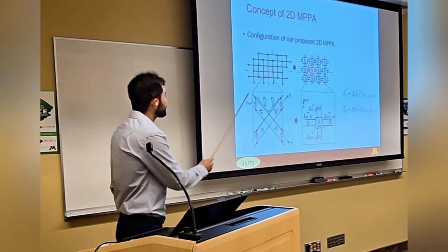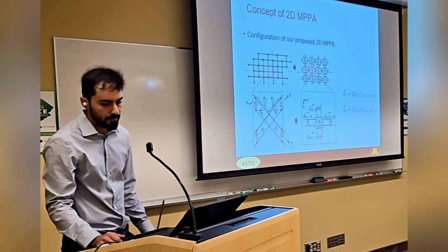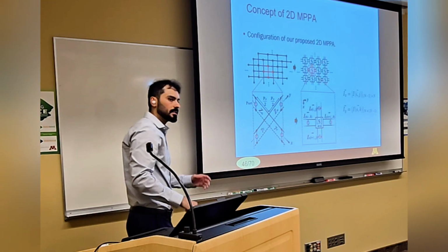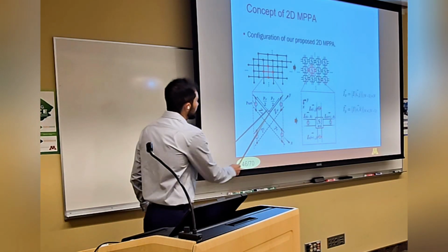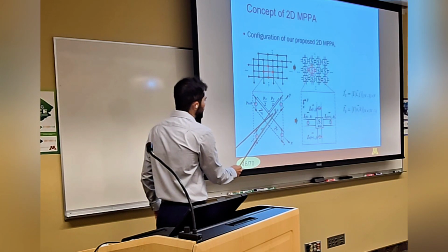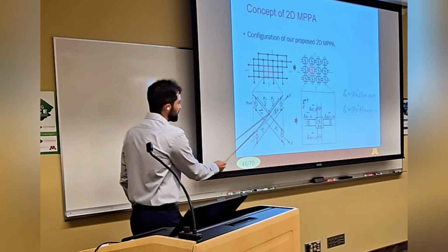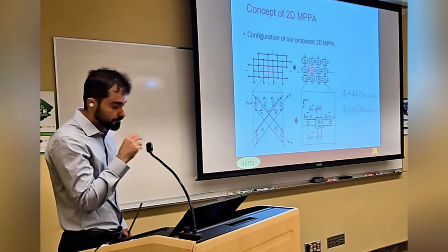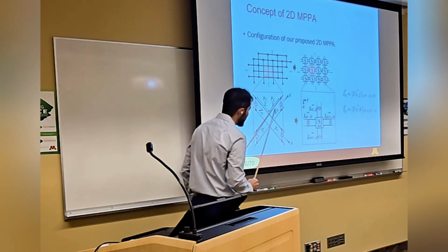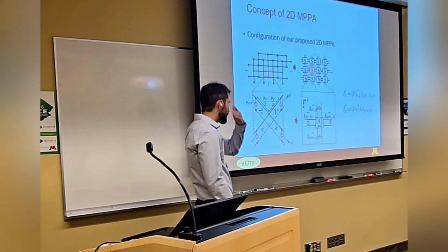This figure depicts the 2D structure, which is constructed from a 2D grid of transmission lines that intersect at the junction point. In this case, to simplify the analysis, we consider a unit cell that has similar characteristics in two directions. I mean, for example, the characteristic impedance of the transmission line in X direction and Y direction is the same. Also, we treat this unit cell just as a 4-port network, and we use just its S matrix. And we have no idea about the physical shape of the antenna in all of the design process.